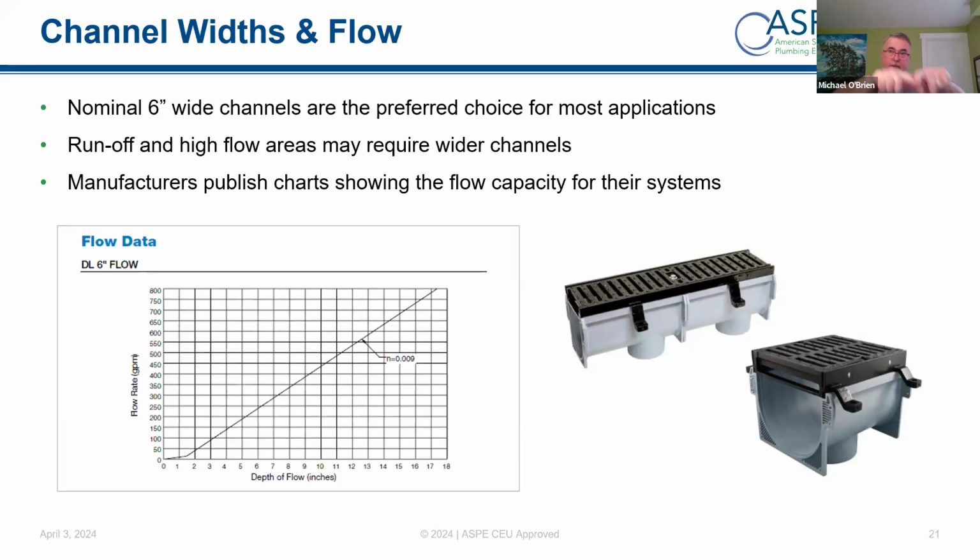So they'll have kind of a square rectangle area. There'll be an outlet. The outlet will have a plug most of the time, and then they'll have that channel designed to handle the amount of fluid or liquid that's in that particular tank. So if it's a 20,000 liter tank, that trench drain is designed to hold 20,000 liters.